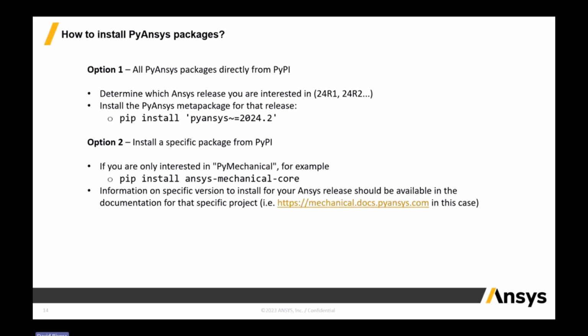Next one, how to install PyAnsys packages. Roberto? Yeah, so PyAnsys packages are simple Python packages, and just like any other Python package, you would use either pip or conda. In this case, PyAnsys packages are delivered through PyPI, so we recommend the usage of pip, of course. Now, there are two main options.